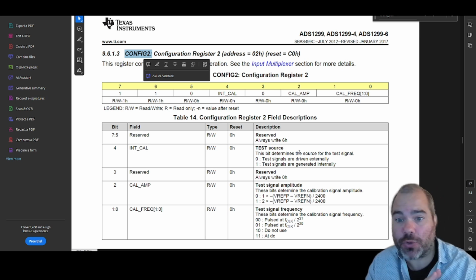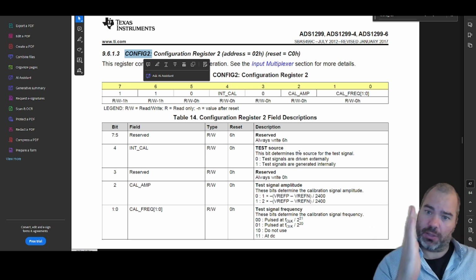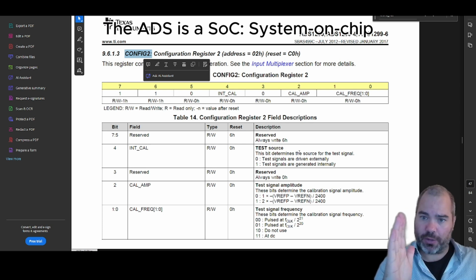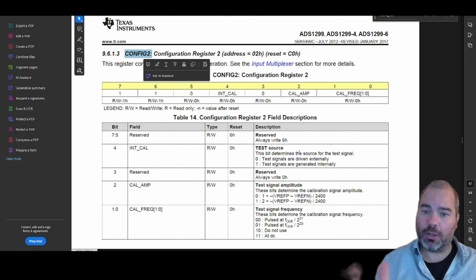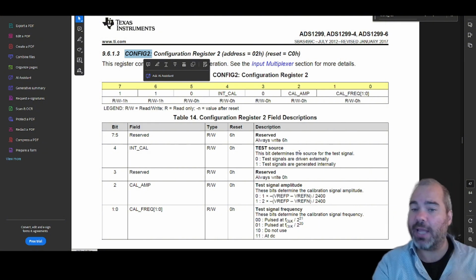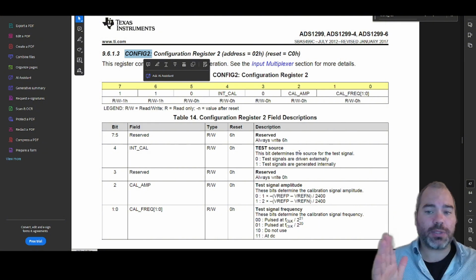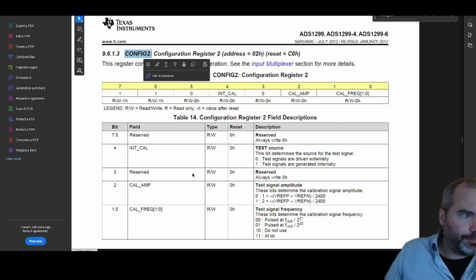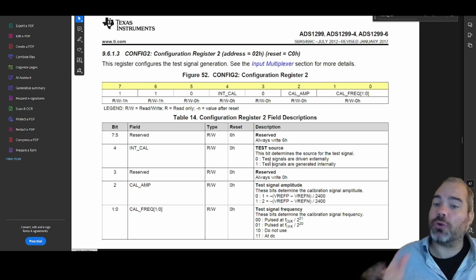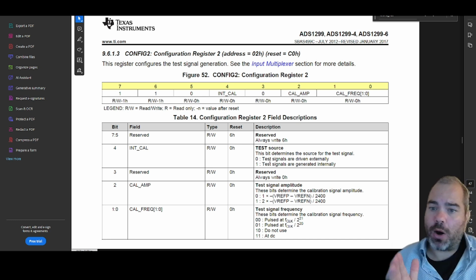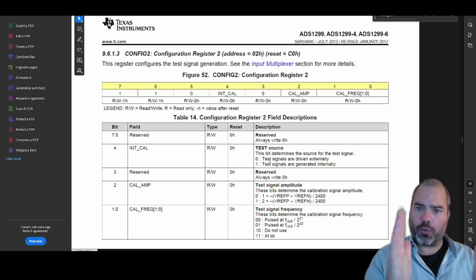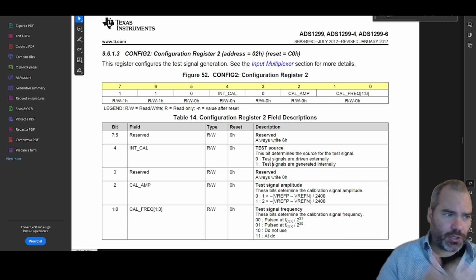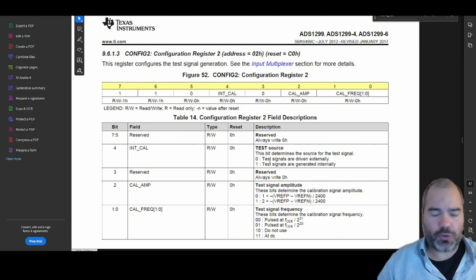So you can ensure that from the SoC, the chip, all the way to your software, you have a known signal with known properties in terms of frequency and amplitude, so you can validate the whole sequence of events from there. The dev did try the test signal. I just don't know if he spent all the time required to ensure that your square wave is always the same length up and down, the frequency matches your expectations, and the amplitude matches your expectations.